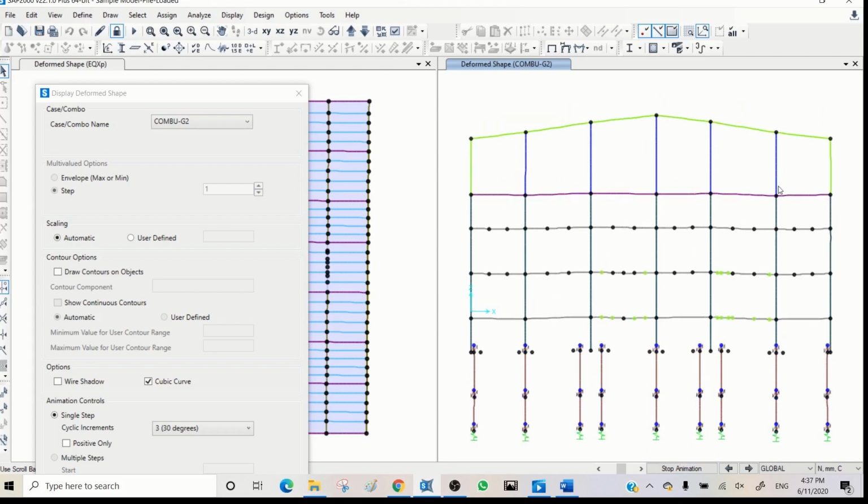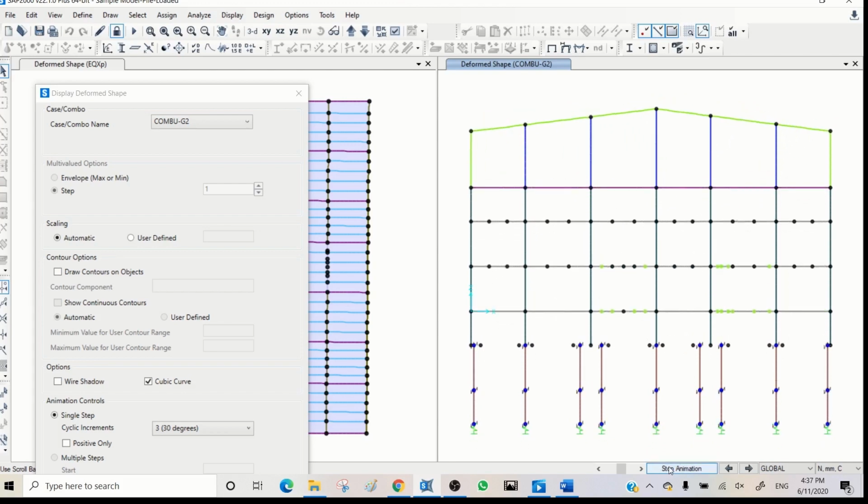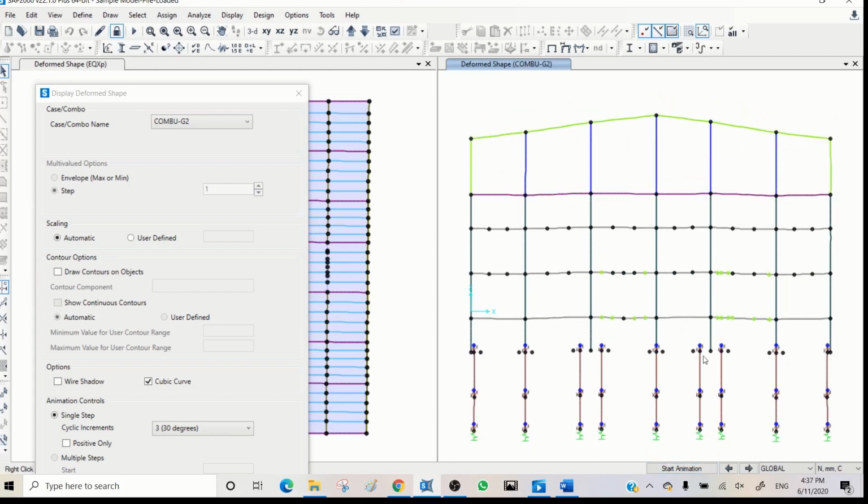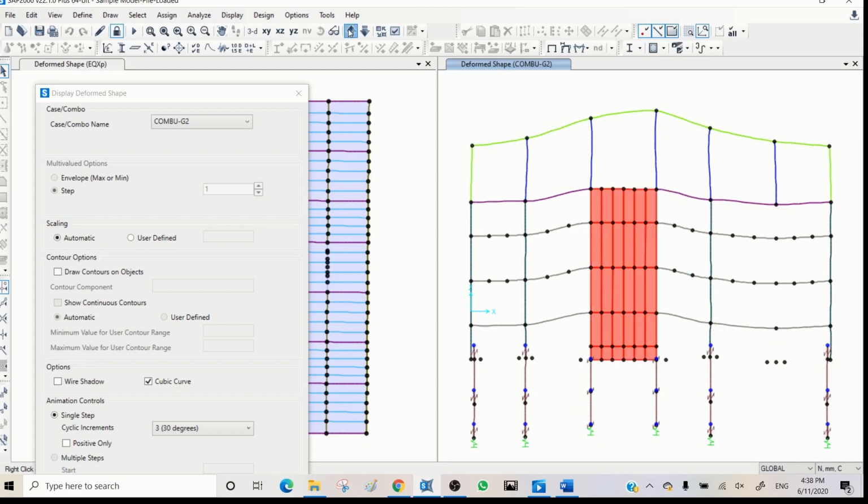difference in displacement here. The reason is, if you remember, we just for practice added 2 piles for some columns and added 1 pile for some other columns. Actually, the loads are pretty similar, spans are similar. So when you put more stiffness for some of them, you see the displacement is not regular, and you see the difference between these two. Now let's move on to other grids.